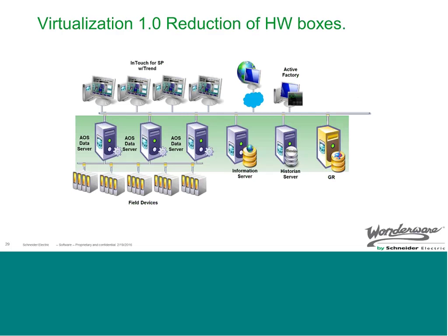Just to take a look at what consolidation of hardware looks like. Maybe in a larger implementation of Wonderware that has more load balancing and redundancy and spreading out of software for easier maintenance, you might have 3 object servers that are responsible for doing the data collection from the PLCs and doing the alarming and providing the data to the HMI.